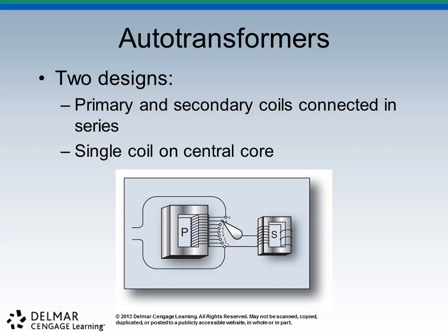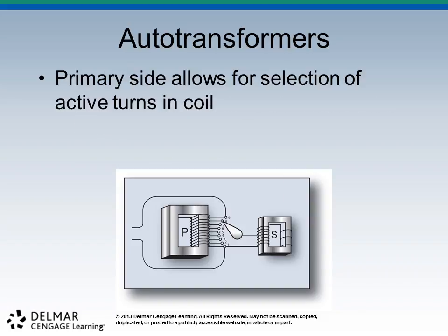On this illustration, this happens to be a step down, just so you know. Too many coils here, less coils here. So we're going to step down in voltage. In A, like I said, that's a step up transformer. More coils on the secondary, less coils on the primary. And we use those auto transformers to help make sure that the electricity that comes in from the street is of sufficient voltage. Let me go back to a better illustration.